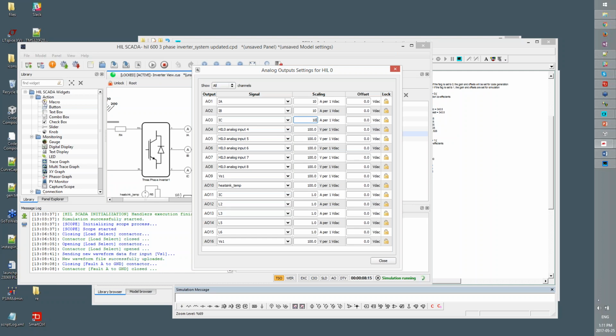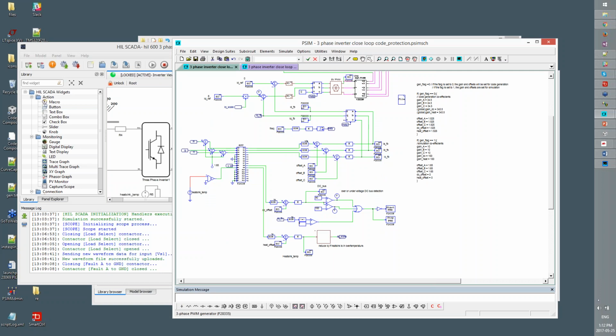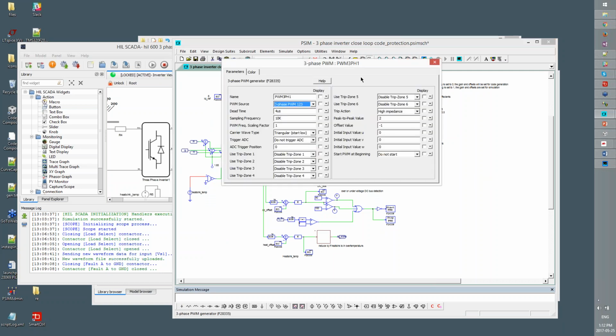Referring to power electronics, can the three-phase inverter nonlinearities due to dead time, propagation delay of signals and finite switching time of real devices be analyzed and perfectly compensated? So the kinds of questions you're asking there, nonlinearities with regards to propagation delay, finite switching time, and dead time. With dead time, you can observe the effects in these simulations, as long as the dead time resolution, like this 4 microseconds here, is big enough to be sampled by the HIL system. Exactly, so that is your limit there. Otherwise, it'll be unobserved.